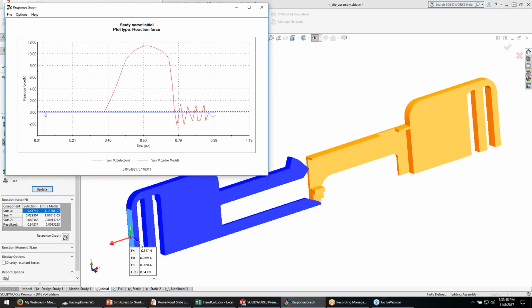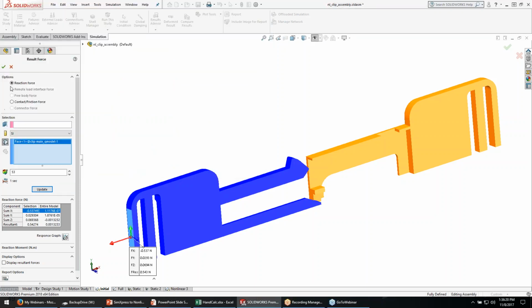You can see the force required. It increases, flattens out right about there, and reading down here in the bottom it looks like about 11.4, 11.3 ballpark newtons. That's when it hits its theoretical maximum, and then it starts decreasing from there and drops off. So 11.3 ballpark it looks like.